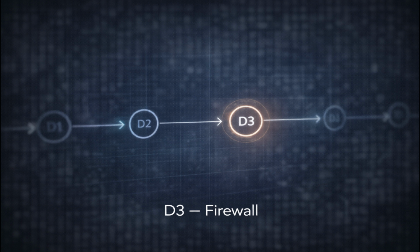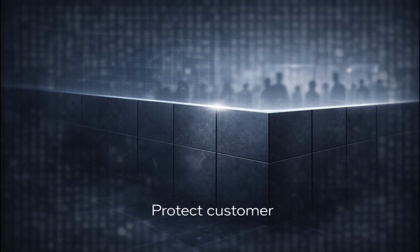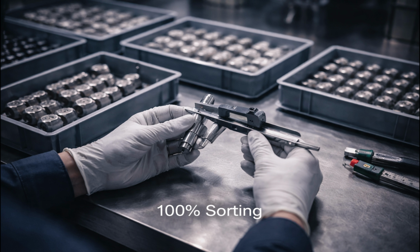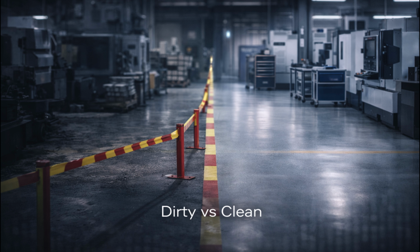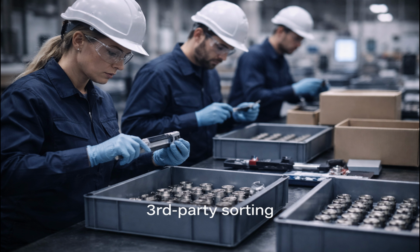Now, D3, the interim fix, the firewall. D3 is simple in logic and strict in discipline. Protect the customer behind a wall until you find and fix the root cause. This is where 100% inspection or sorting kicks in. Physically separate dirty versus clean areas. Add an extra inspection station at end of line if needed. Bring in third-party sorters when appropriate.